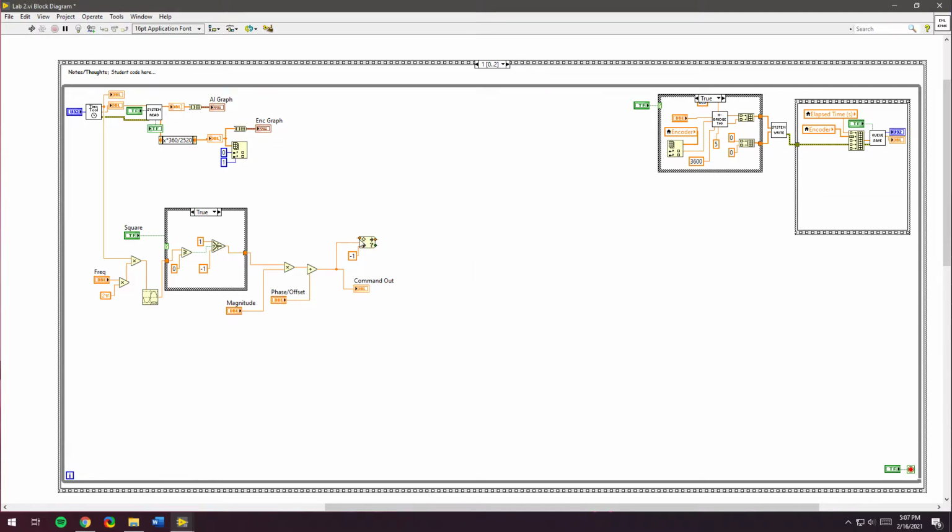On the top, the upper limit, right click, create constant. We're going to do 1. I'm going to right click on the actual item and do include upper limit, just so that 1 is inclusive. And then we can run this coerced X up to our H bridge, since this is the command that we're sending our motor.